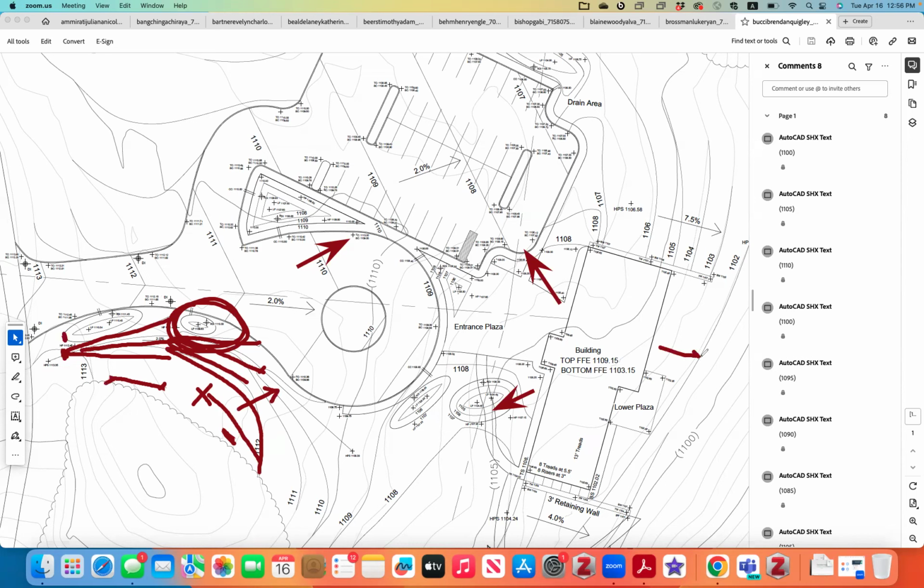You need slope for the back plaza. Here I would probably just use maximum because it's not necessarily uniform. Same thing over on this side. You need slope arrows for the swales. Okay, for the swale center line, you need that. This is wrong. Your slope is going this way, okay, at 2%, right? So essentially, all your uniformly sloped area needs a slope arrow, okay?